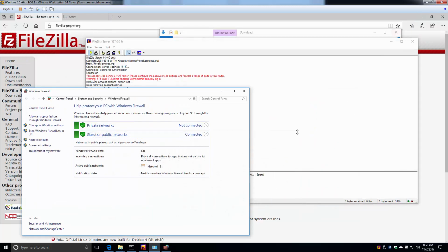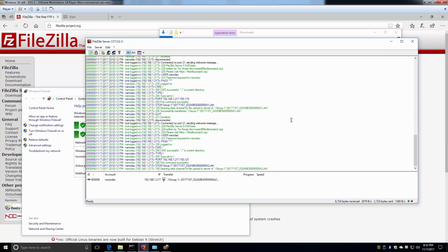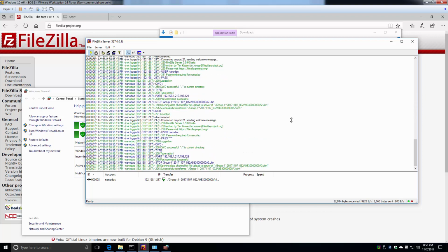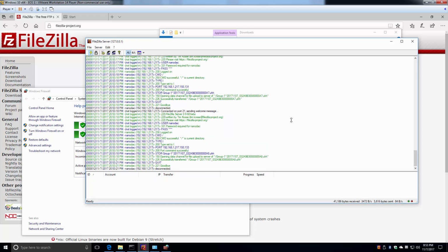So back on the nanodac, it did say that it failed. Let's go back and let's do last hour again. That was it. That was the problem. So again, bringing somebody within IT is always key here. Again, it's not like this on Windows 7. It's actually a little bit more simplistic, but Windows 10 is a little bit more locked down. So something to keep in mind, guys. FTP firewall usually comes into play here.